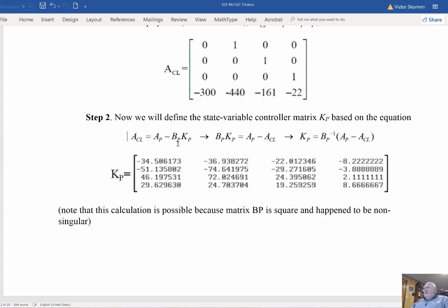Okay? How did we handle the situation earlier? We were taking advantage of the canonical controllable form. With a row matrix of the controller, we should be able to handle only the last row of the fundamental matrix of the closed loop system. This expression enables us to handle the entire fundamental matrix of the closed loop system.